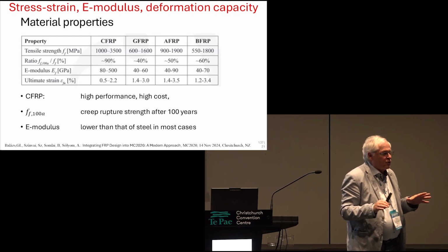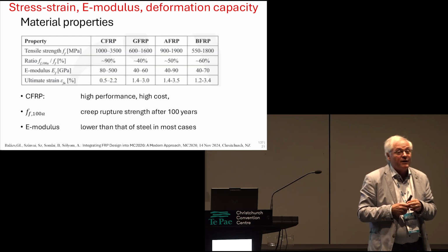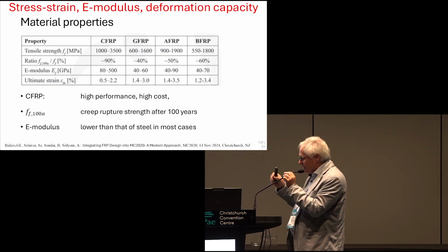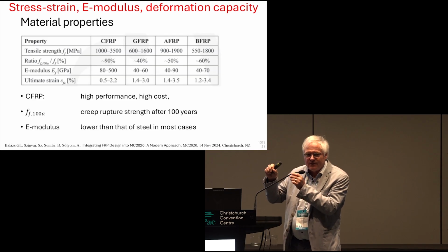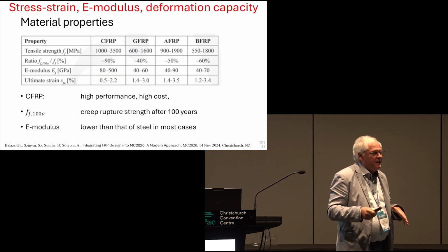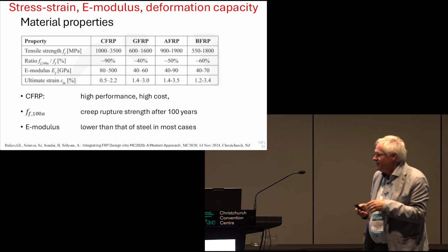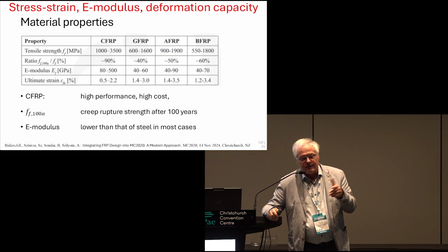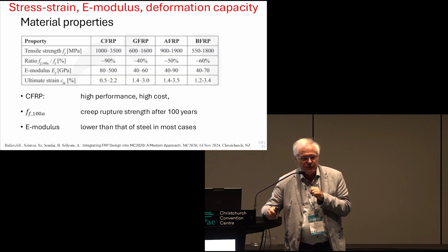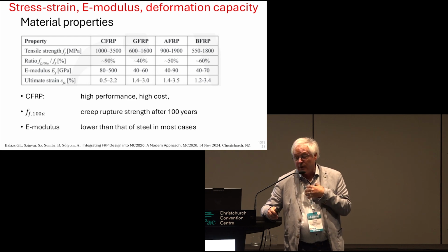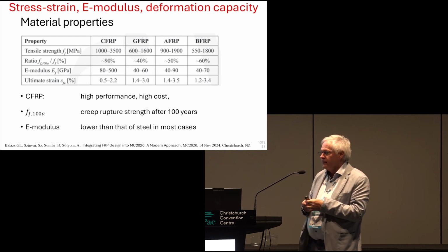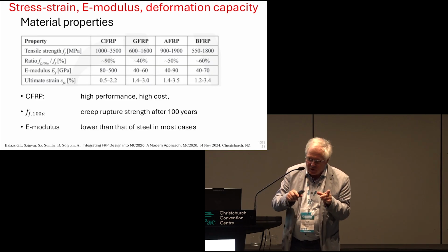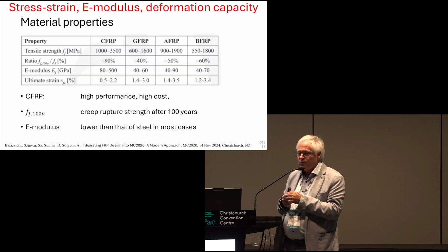There was a very long discussion, and we are very happy that the industry also supported the solution that when we apply the strength value in design, we have to apply the long-term value of the strength and not the starting value of the strength. There are considerable differences between these values. There are many tests, and we are also running these tests, with of course different results using carbon fibers, glass fibers or aramid fibers.